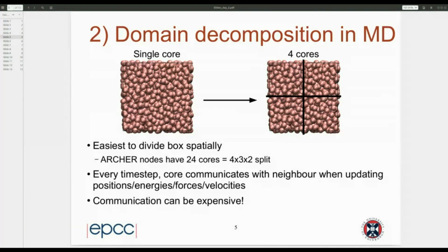The reason I chose 24 is twofold. The first one is, while there's an increase in communication cost, I'm aware that the simulations still run faster at 24 cores than they would at 12. And secondly, even if I only did 12 cores, I'm still paying for 24 cores, so I'm only using half of what I'm paying for. But either way, this simulation is not a good use of resources. I hope that answers the question. Cool.